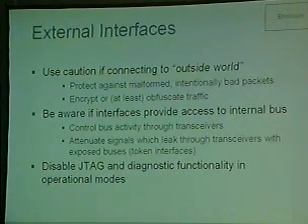So you need to be aware of what data is being sent out of those ports, possibly encrypted if you can, that would be good. Also be aware if any of your external interfaces provide access to the internal bus. That can give a lot of headway for the attacker.